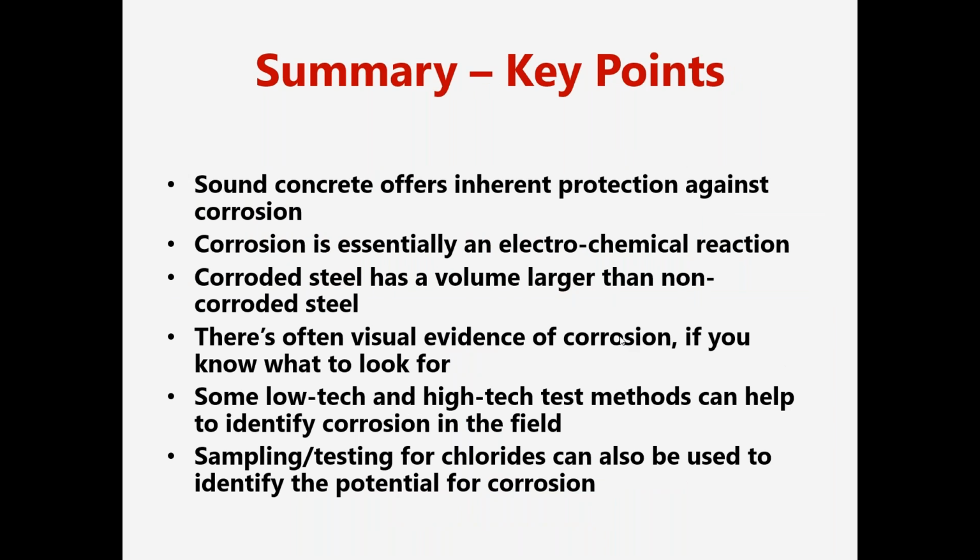So we just want to summarize a few things that we've talked about. Sound concrete offers inherent protection against corrosion. That's the passivity layer that Chris talked about. The high pH, 12, 13 on a pH scale. We know corrosion is basically an electrochemical reaction.